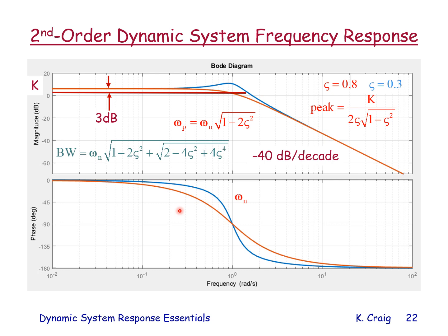Input a sine wave, wait till all the transients die out. The output sine wave will be the same frequency, but the amplitude will be different. There'll be a phase shift. Both the amplitude and the phase shift depend on the frequency. And that's what the Bode plots show. The Bode plots show an amplitude ratio, output over input, and a phase angle between the output and the input.